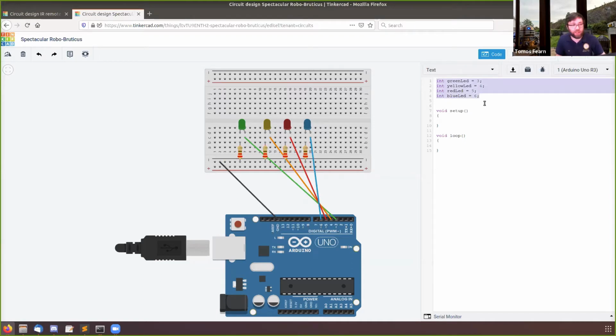We've got those pieces now. What we're going to do is in this startup bit of code here, we're going to tell the Arduino what it's connected to. So with computers, we have inputs and outputs. So LEDs emit light. So this particular component that we're plugging in is an output. So what we're going to type in is pin, and then all one word with a capital M, mode.